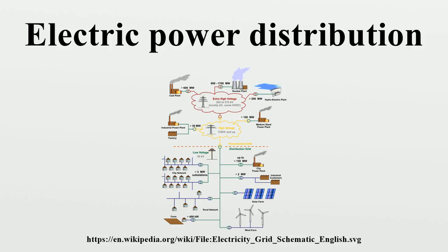In Europe, electricity is normally distributed for industry and domestic use by the three-phase, 4-wire system. This gives a three-phase voltage of 400 volts Y service and a single-phase voltage of 230 volts. For industrial customers, three-phase 690/400 volt is also available. Large industrial customers have their own transformers with an input from 10 kV to 220 kV.